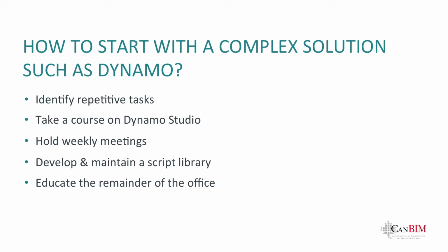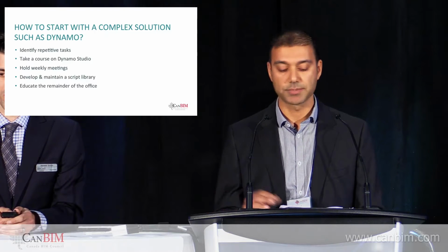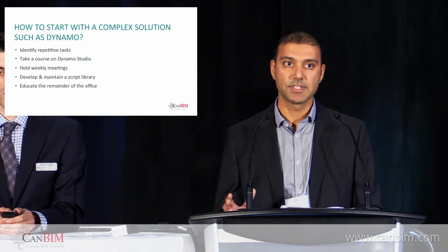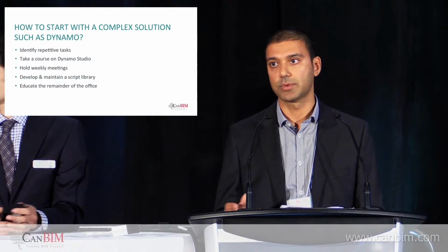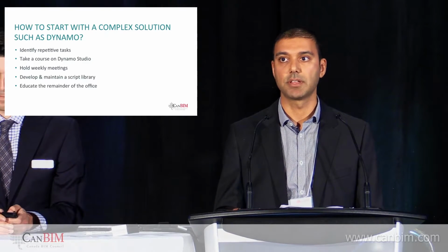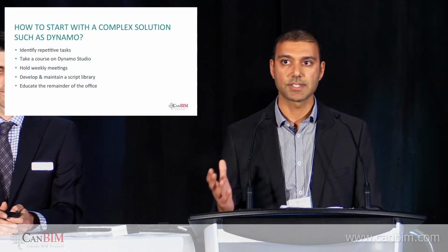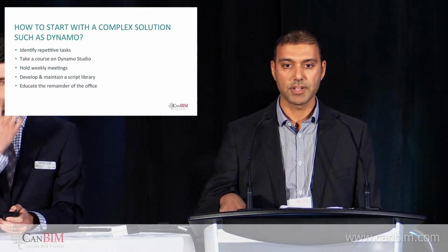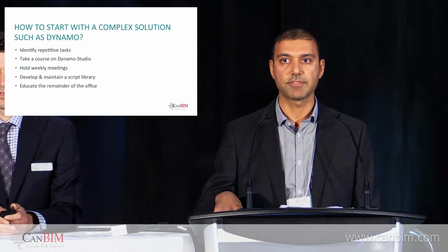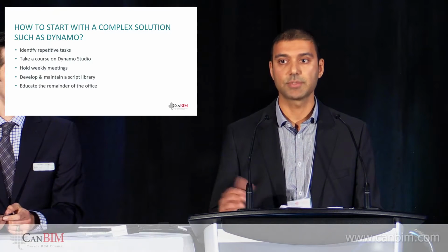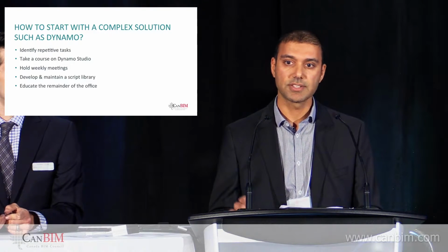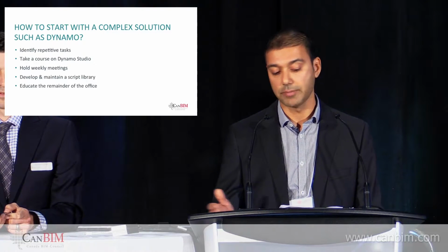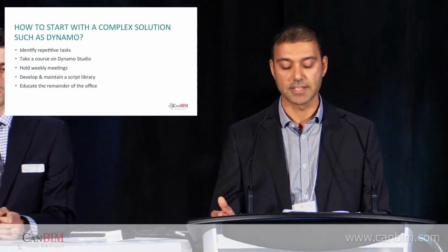So there's going to be, for example, model exchange. We have to share our models with our consultants. And sometimes that sounds easy to do: send us your model. It actually takes more time and effort. You have to detach the model. It could be a giant model. You have lots of sketch views and things in it that you need to remove manually. On some of the giant projects, this can take time. It takes effort, and you have to go through it manually. Well, we have a Dynamo script that takes minutes. So these little things, turning hours into minutes, have a cumulative effect on our bottom line, and hopefully we give a better product at the end of the day.